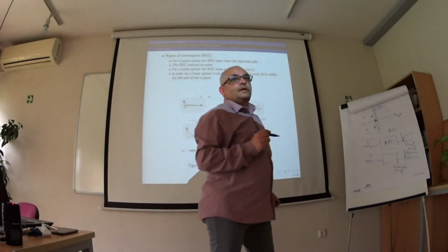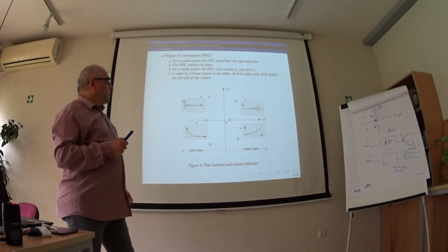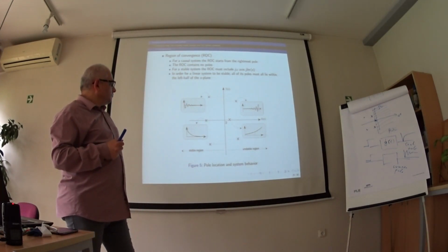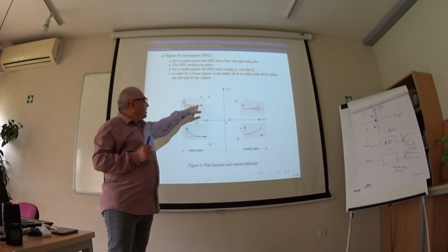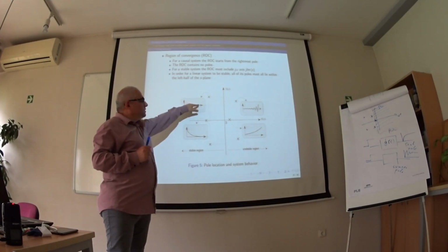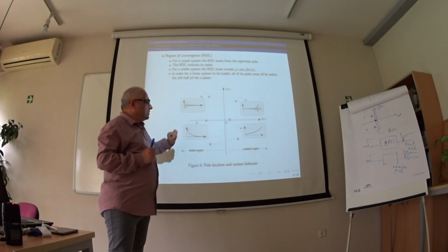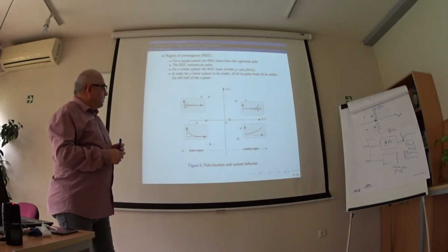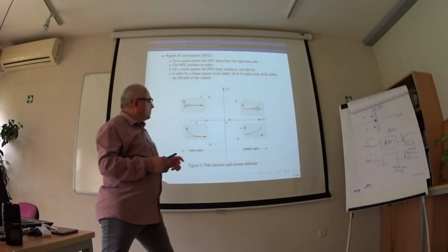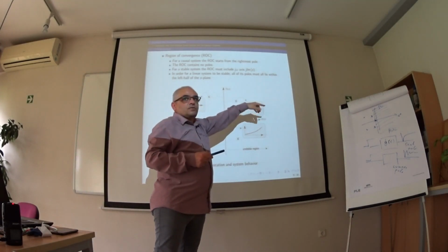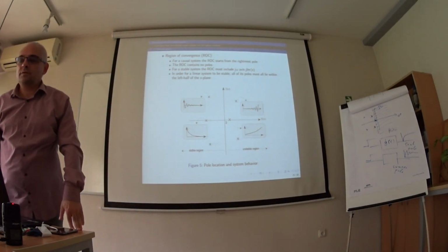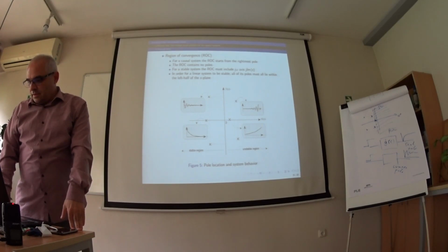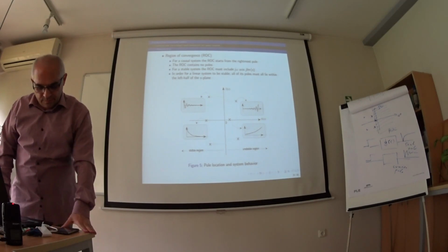It starts to oscillate. If the system is stable, at time when time tends to infinity, the oscillation will be almost zero. But for unstable system, the amplitude of such oscillations increases with time. So as you can see, the pole zero plot is very interesting and can give us a lot of information about the system